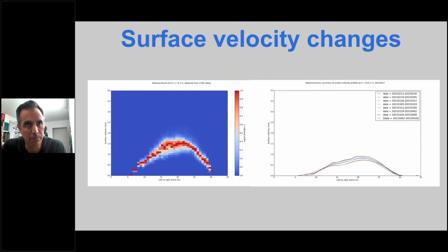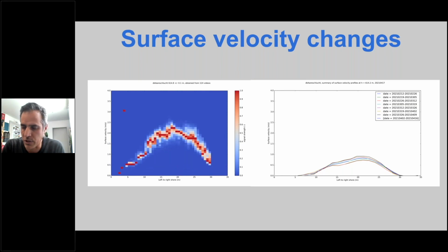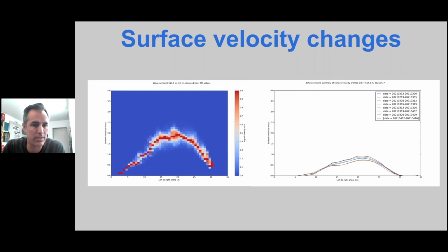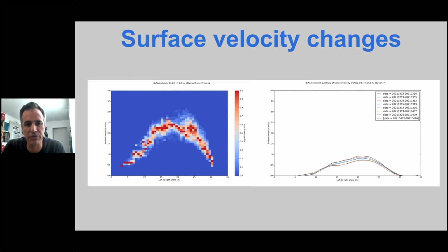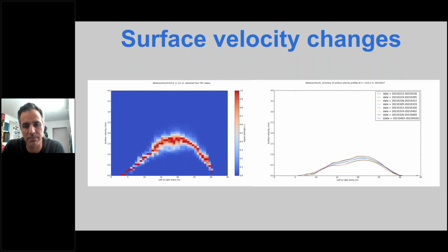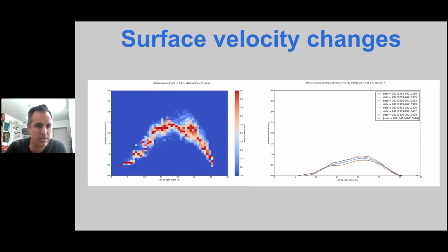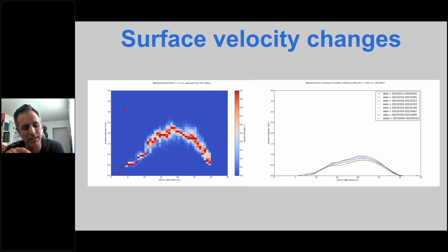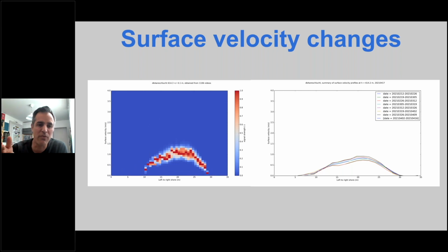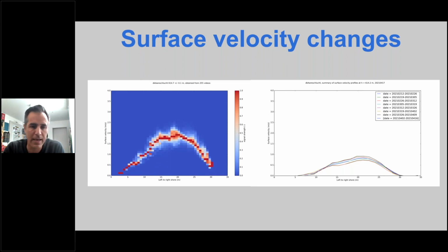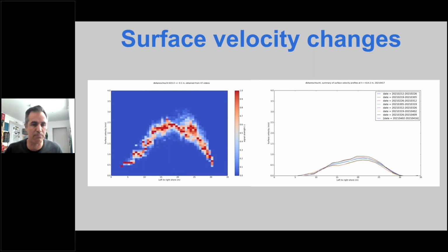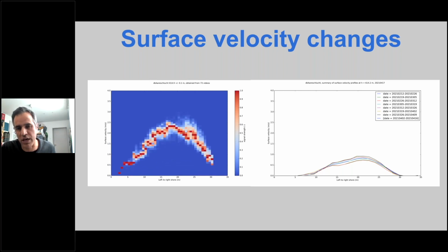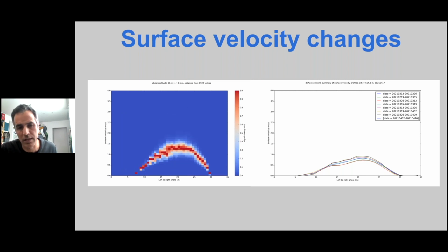So now I want to come back to that velocity envelope to showcase another of the strengths of these methods. In the animation on the left, we see an ensemble of many measurements done at the same water height. And when the animation moves, it represents the surface velocity at a different height. So that's a probability distribution function of the most probable value of those velocities according to a certain water height. So then we start getting a more probabilistic value, not just one measurement. And that can also be used to detect changes in the river. For example, changes in the cross section.